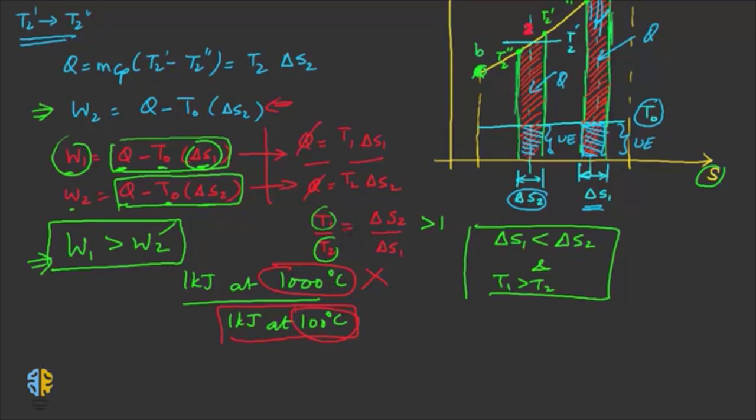So when you have fluids of 1000 degrees Celsius flowing through your pipeline systems, then you may need to add a very adequate amount of insulation. Now this may not be so important for low temperature fluids since the loss of available energy is low. The same can be said that when you have very low temperature fluids, then yes, you have to again add adequate insulation so as to prevent heat gain from surroundings.